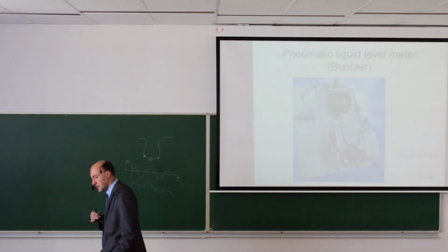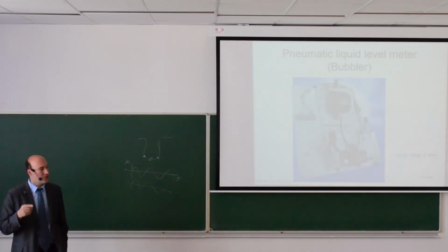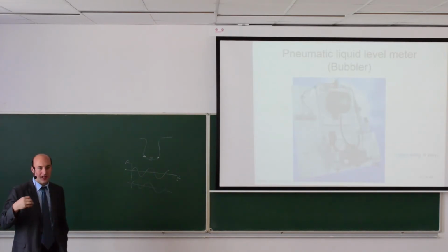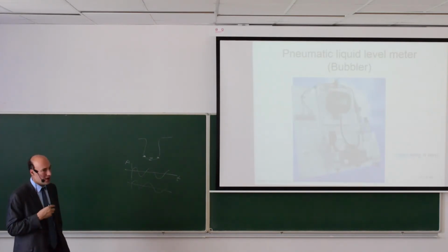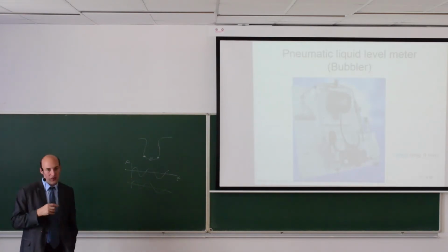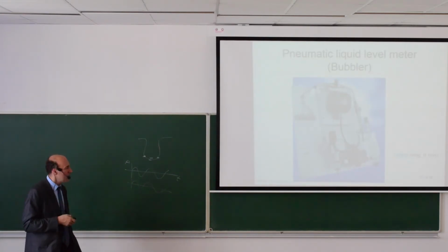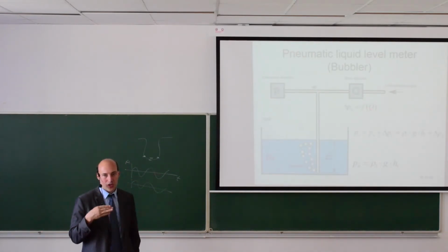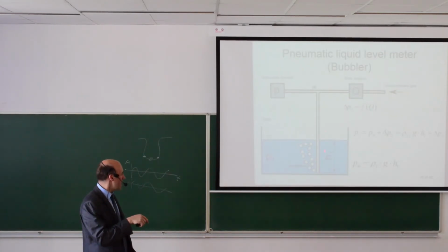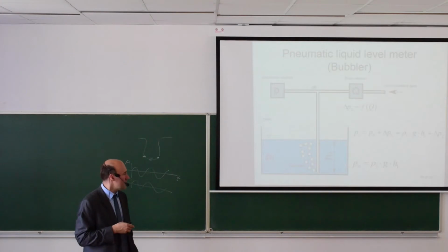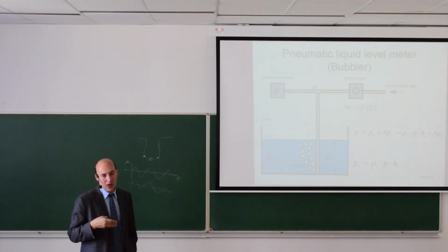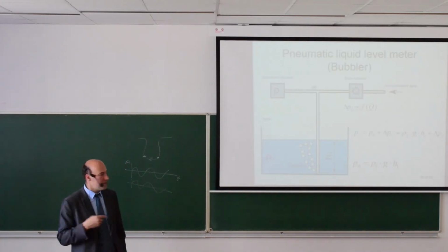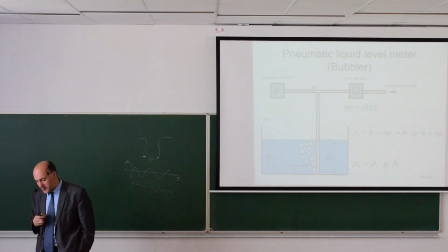So this is a very simple system. You may have seen it in our lab 409. So it's just a tube that is in a tank, and it works very well. But as I said, the process has to accept that you blow the air. Also, you need this source of the compressed air, which can be quite expensive because you are blowing air at all times into the system, and this will cost a lot if you count that for the whole year, for example.